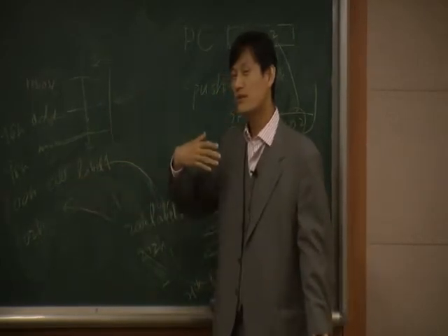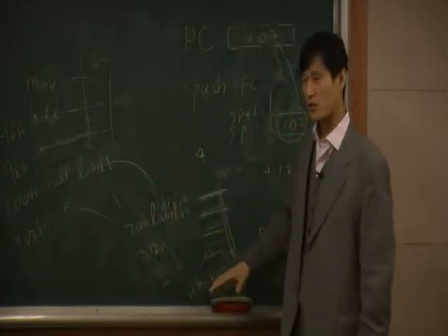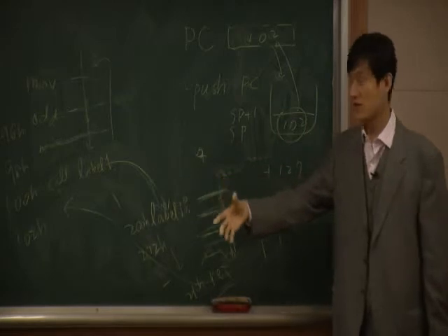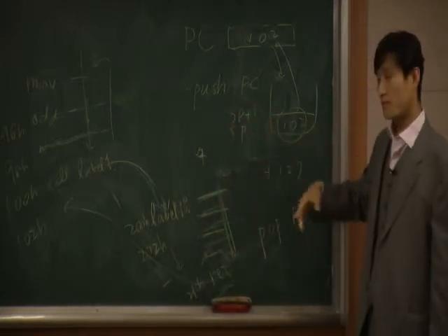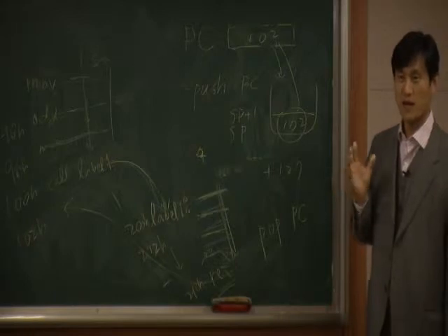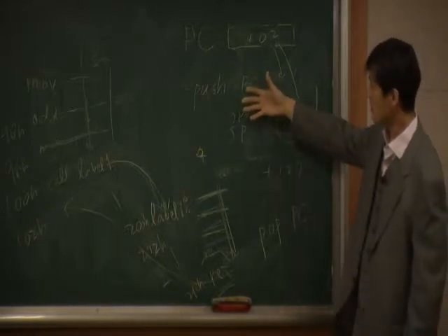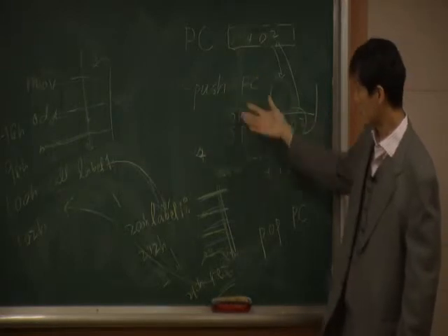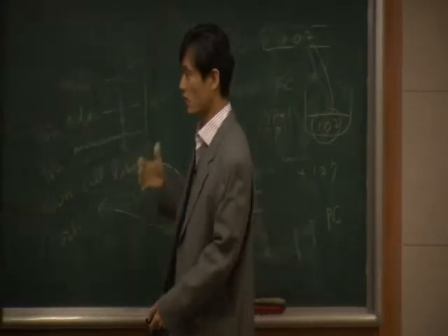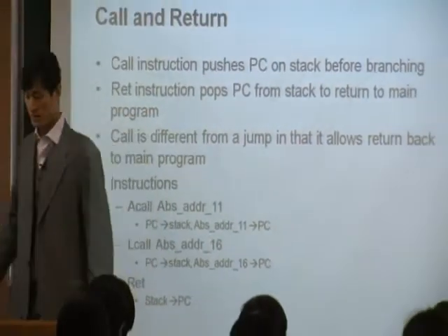What I do is that I just say call and I just say return. That's all I do. The hardware, the microprocessor, does a push and pop automatically. I'm not doing anything. The hardware does it. Inside the hardware, the microprocessor is actually doing push and pop. I don't have to do it. This is automatically done. So that's another nice thing. The hardware does it.